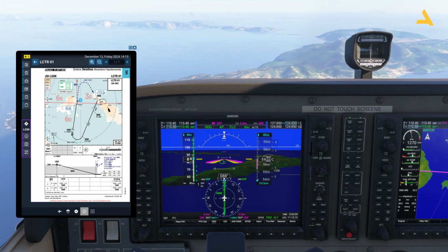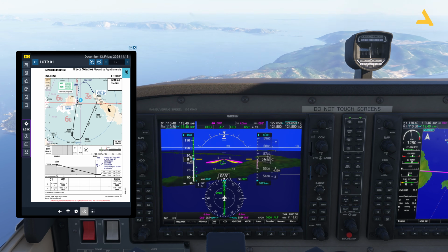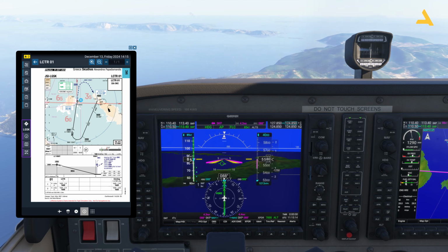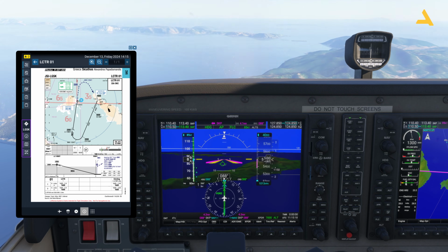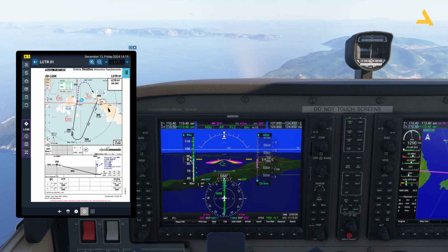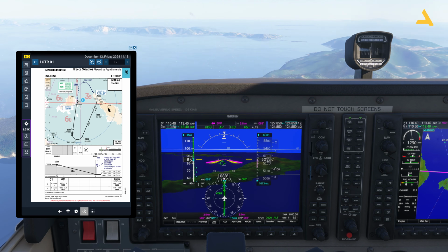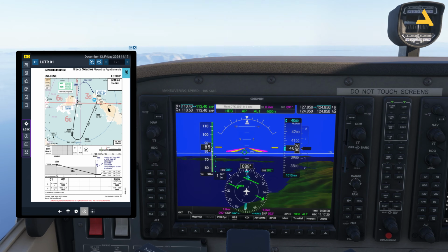Now you have to redo the calculation because I will not be doing this maneuver at the earlier speed. So let's divide 85 by 200 and get a new distance. It's again 0.4 nautical miles. Not a big difference, but as a precaution, I will just turn right 0.5 nautical miles before this VOR. Now just 1 nautical mile to go.